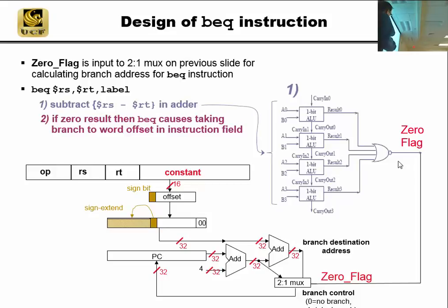So you're telling me this is all the hardware inside for this instruction? Actually, yeah, for implementing this instruction, yes. There's other things that we need to make this instruction execute, like we have to go to memory and get it, and we have tri-state buffers and turning things on and off in the buses, but inside the ALU to implement a BEQ instruction, you only need a subtractor, a mux, and a couple of adders. Now, question, is this adder different than that adder? Yes. You know, this is a separate piece of hardware, right? But they can be designed the same. This can be ripple carry, this could be carry look ahead, this could be whatever, depending on how fast we want to make it run.